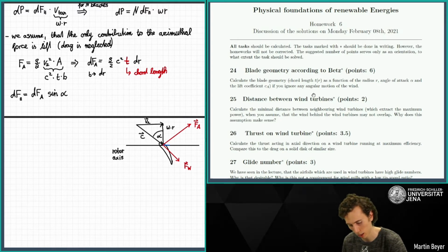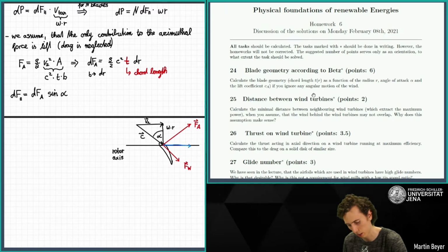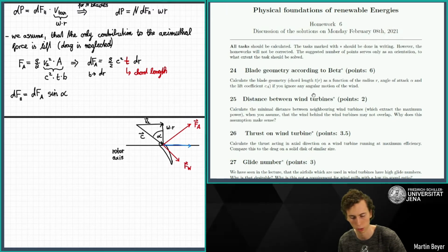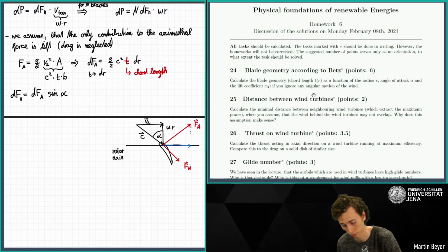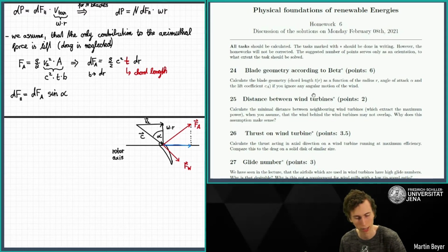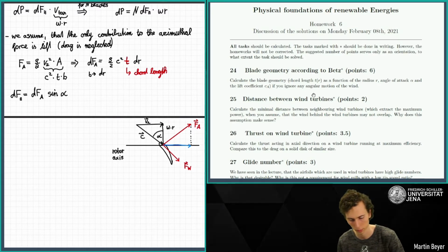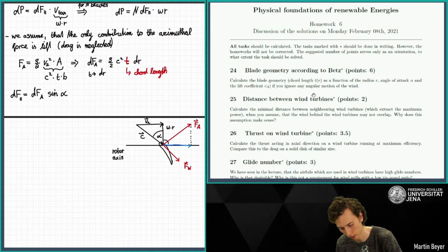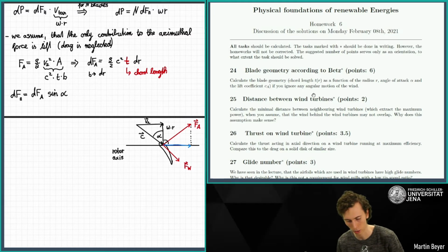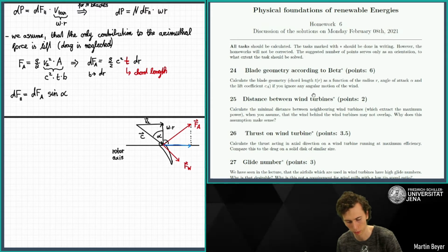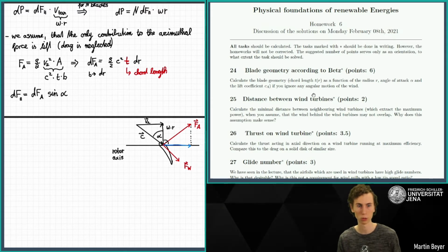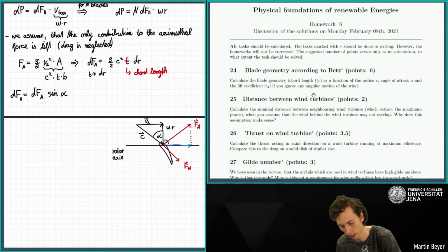We find this parallel component just by looking at the projection onto the rotor axis. Noticing that the rotor axis is perpendicular to the rotation direction omega times r, we see that here we have a right angle. Also between the inflow velocity c and Fa there's a right angle, so we will find the inflow angle here again.